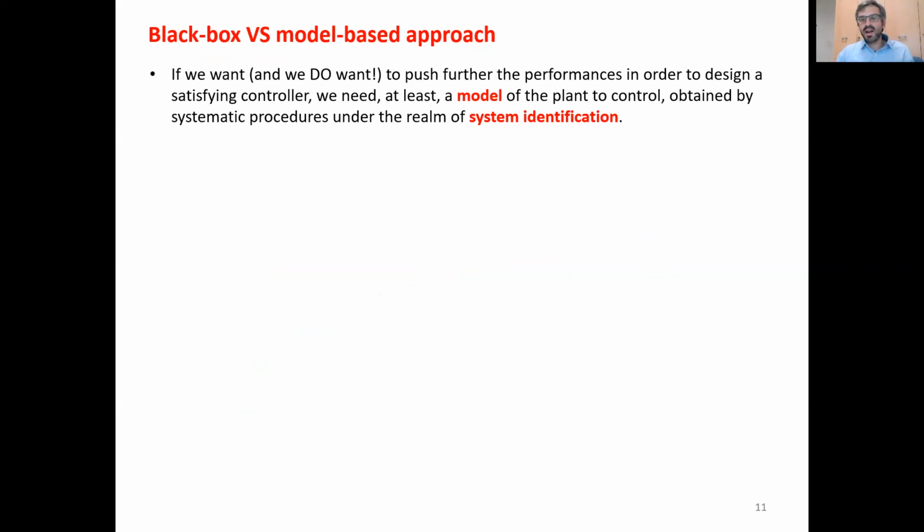In general, to derive the model of the plant, we write down equations, as we did, based on our physical intuition, and then identify the parameters of these equations, creating some trajectories and measuring both inputs and outputs. This procedure is called system identification.